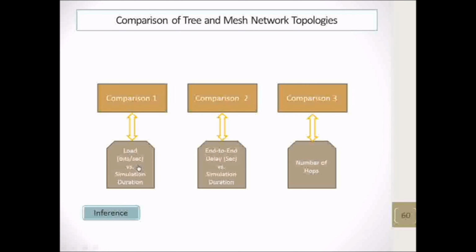And similarly the output from the PC is minus 8 volt, and after conversion it is 3.83 volt, so that the Zigbee can correctly transmit to the Zigbee of the forest area module. Now the final results of Zigbee and RS232 conversion are tabulated. Now the hardware has been set up. Next we will see the required signals for transmission.